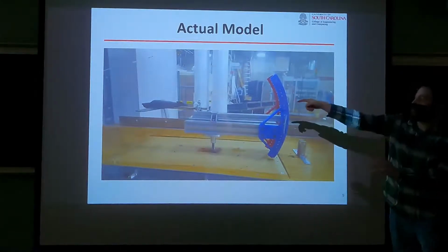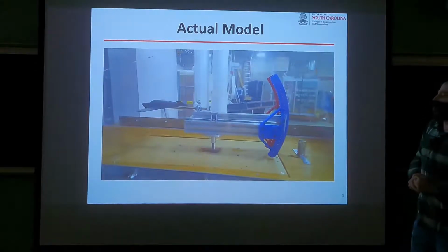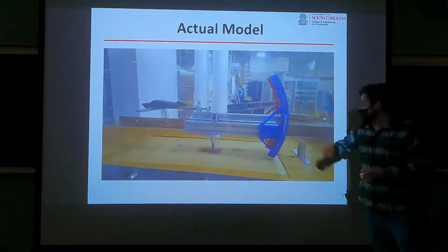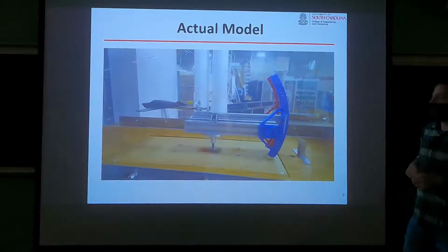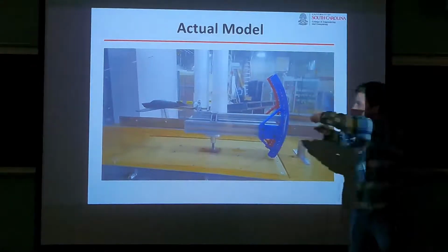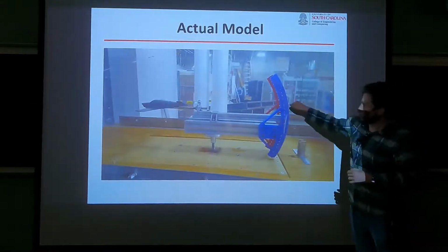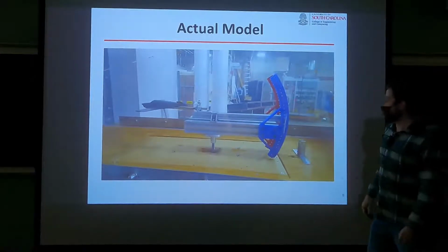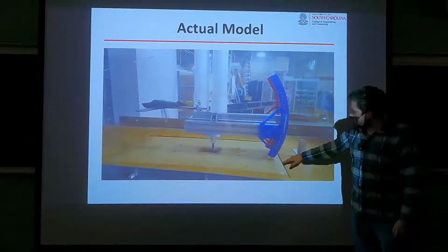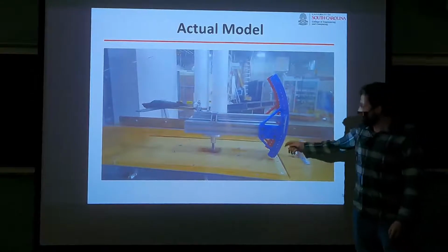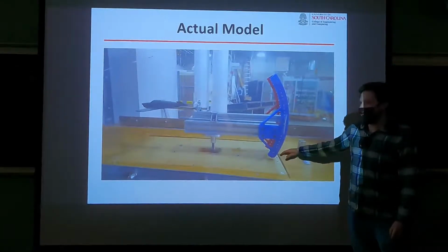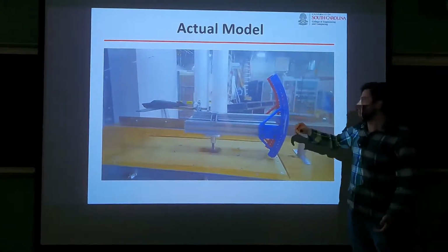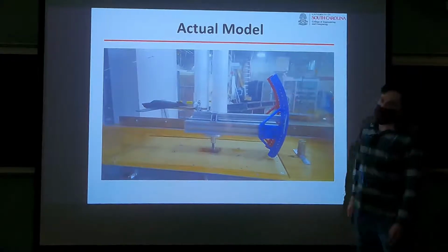But you can see the Beach Bonanza model mounted on the front. All you do is pull the bolt out from here. It has a wing nut on the back of it, and it's pinned in the center. So then you just rotate it over and pin it back up. We were limited in our Z on the bottom, so we only went to 30 degrees for the positive angle of attack, and we went to negative 35 on the top.